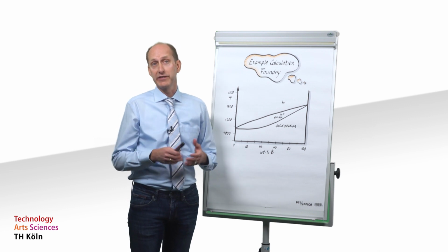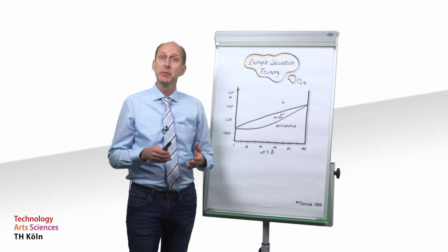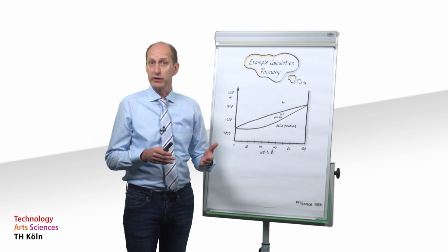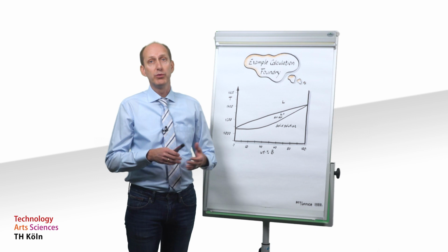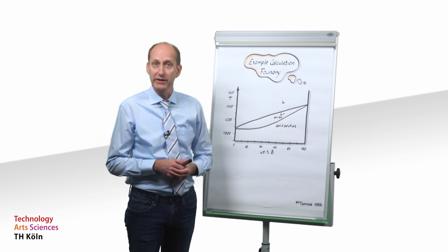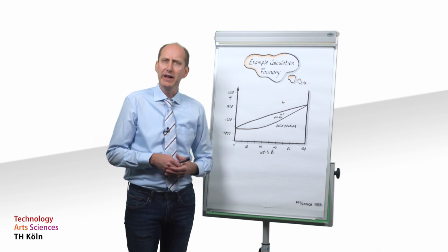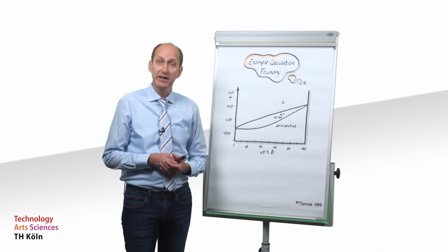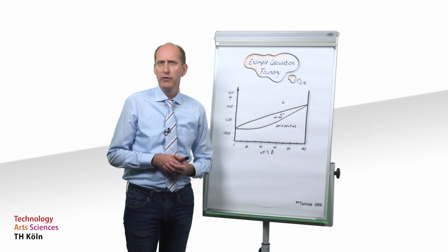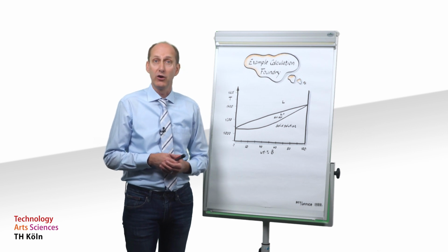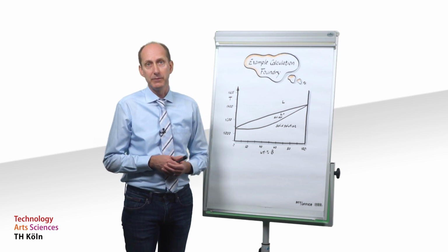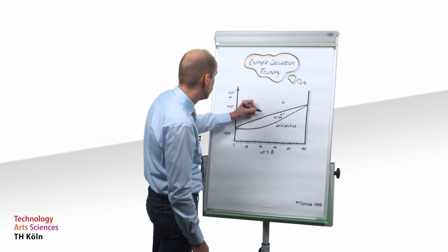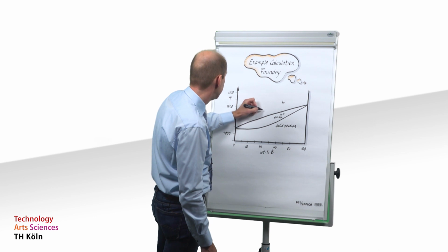Let's go through a short example calculation. The problem is as follows. Determine the start and the end of solidification, the composition of solid solutions and melt at 1200 degrees Celsius, and calculate the amount of solid solutions and melt at 1200 degrees Celsius for 500 kg of an alloy with 40% B. The points of intersection of the vertical with the liquidus